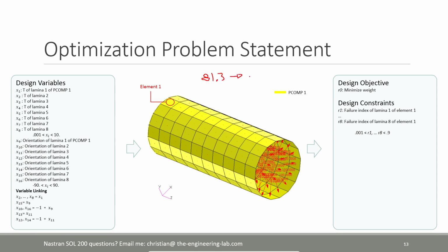We want this in increments of 5. So here, we expect Nastran to either produce an orientation angle of 80 or an orientation angle of 85 degrees. This could be for any other number, so it could be for 13.3, or here 13.4. Any other number, it's going to try and get you a value that is an increment of 5.